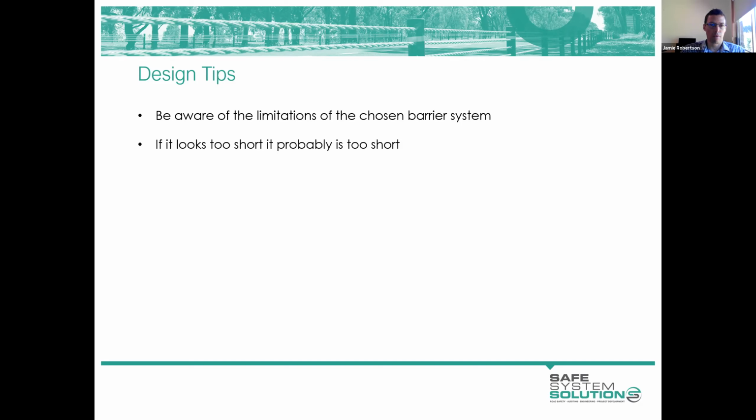Minimum lengths of barrier are really, as we've seen, really quite large. So be mindful of those when you're designing and installing barriers. The length that you have available might influence your choice of barrier system. Avoid short breaks in barrier where possible. Short breaks leads to more terminals. So it can be the case that providing a succession of short barriers instead of one long barrier is actually a more expensive outcome.